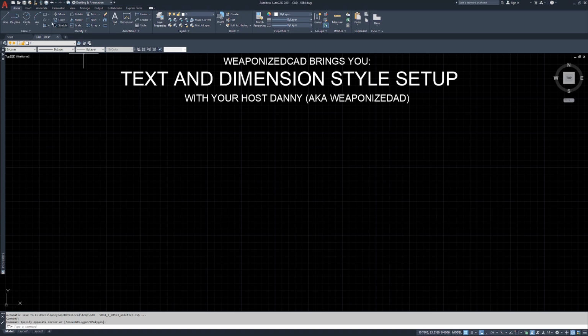So for text and dimension styles, we are going to be in the Home tab, Annotation panel. Need to add text, you can simply click the big A. The big A gives you multi-line text, which is also referred to as M text. Multi-line text can also be keyed into the keyboard, M-T-E-X-T.